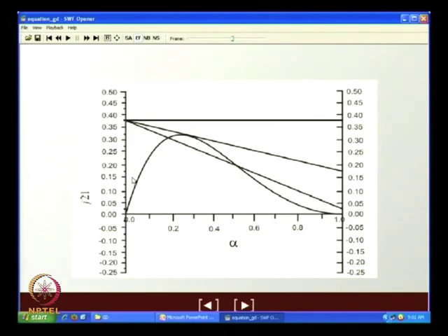Do you get the point? For each particular alpha, there will be one set of J2 and J1 under which flooding will occur. So, for each alpha, if we get J2 and J1, then we can locate each and every point, isn't it? We will find out what is J2, we will find out minus J1, and then at that particular alpha, the point of intersection of this alpha with the straight line will give us one particular point in the curve.